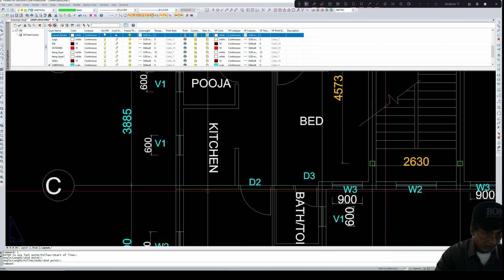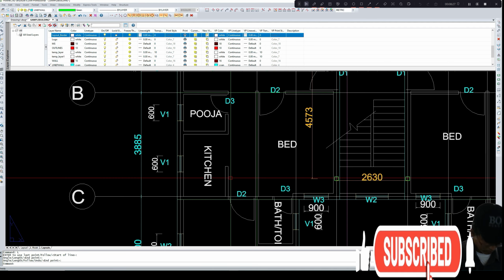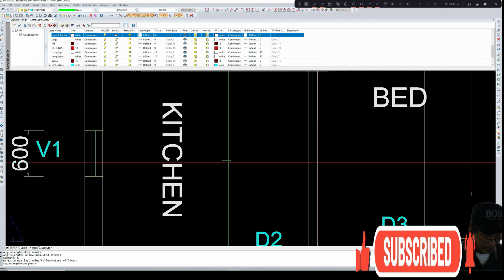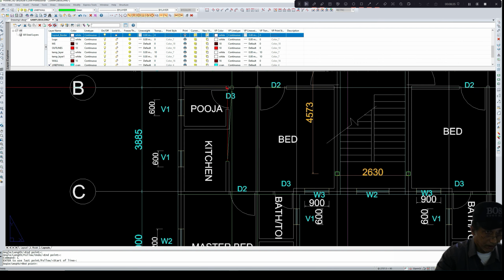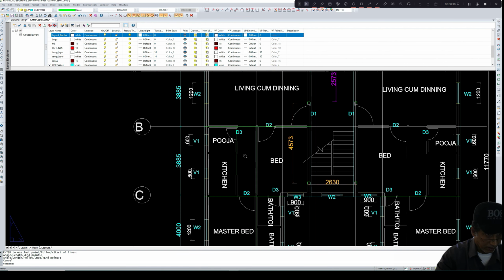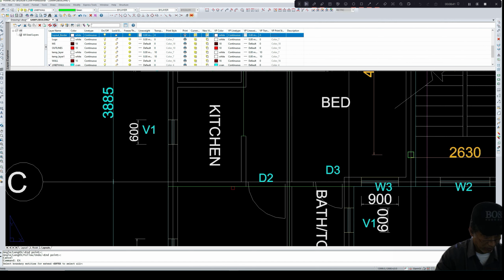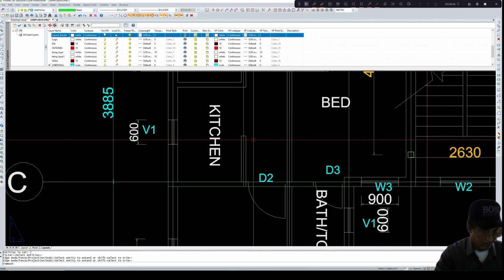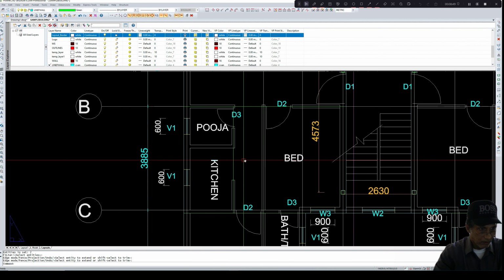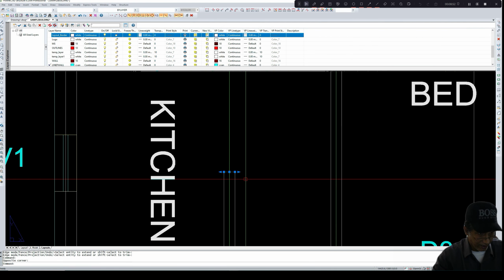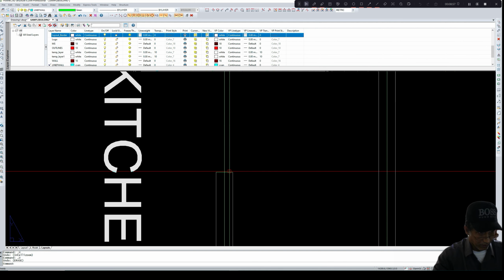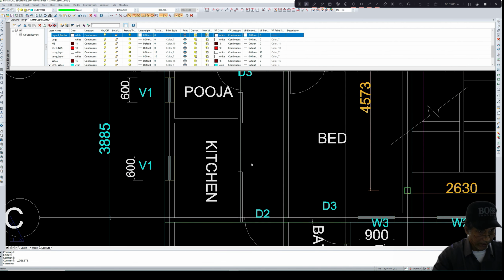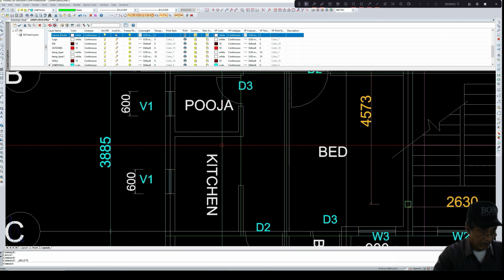Again there is one more wall, so let us draw a line to have a center point. Let us take a line from the midpoint and drop it here, then extend this line to the other internal wall. The command for it is EX. Let us delete this line. Ctrl Z. We should click it and then delete. Then the white double layer line, the temporary layer line, will be there.